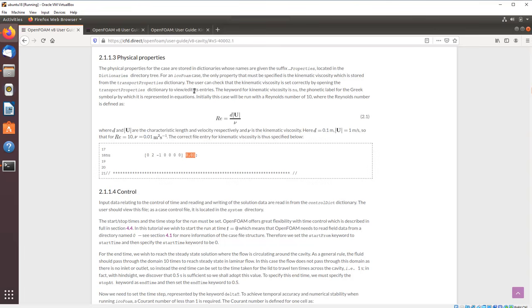It's probably just some kind of ideal fluid, which might be water, might be something else. We are defining this viscosity based on the definition of the Reynolds number, because we want to stay in a laminar state. So we want to be sure that the Reynolds number is low enough so that we are in laminar state, and the value we'll take here for the Reynolds number is 10.